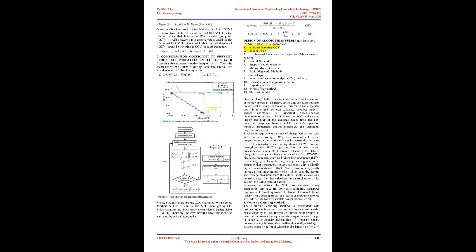In practice, the criterion can hardly be achieved due to the complex operation condition of EVs. To address the issue, a looser criterion is employed. This criterion denotes that if UP1 and UP2 approximate to the steady state in an adjacent time domain, their mean values will also be close to the steady state. Namely, the battery is in quasi-steady state. The restrictions for the mean values are aimed to eliminate the misjudgment caused by the oscillation in I(k).